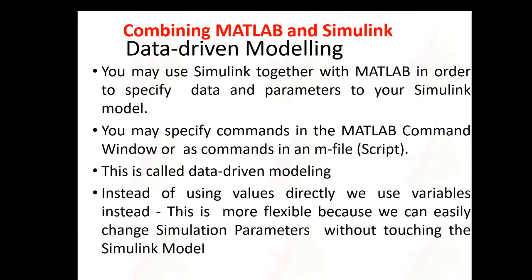Another important thing, as I told in the beginning itself, is that you can combine Matlab and Simulink. That is data driven modeling. The name of this is data driven modeling. You may use Simulink together with Matlab in order to specify the data and parameters to your Simulink model. From the M file, you can send the parameters to the Simulink. You may specify the commands in the Matlab command window or in the M file. This is called data-driven modeling. The data is driven from the M file for running this Simulink file.